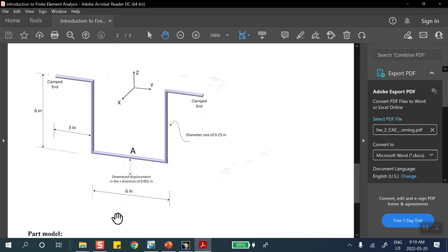you may not know what to put for the restraint here. Okay? Not only did you not see symmetry, but maybe you saw it, but you did not know what to put as the restraint. Okay? The rule for the restraint, we discussed it. If xz is a plane of symmetry, no translation in y, that's easy, rotation, opposite.